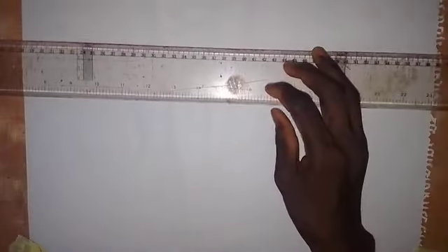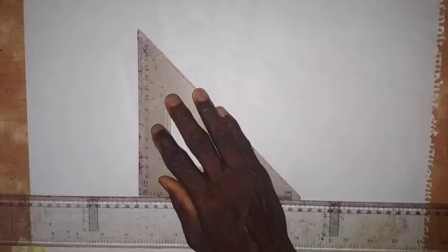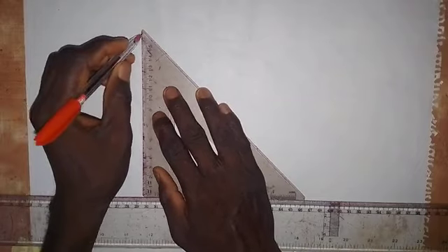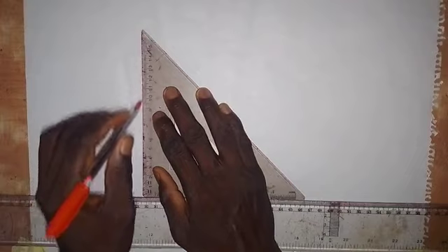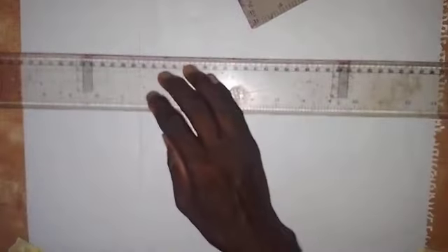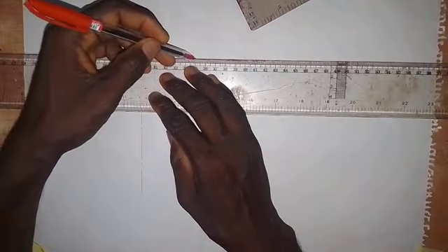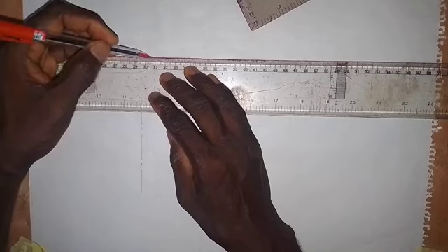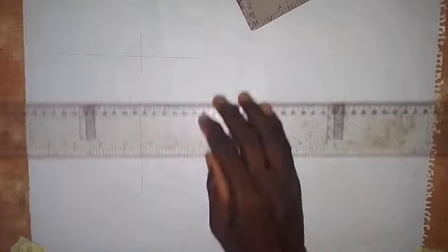The first thing that we are going to do is draw a vertical line. So let's draw a vertical center line first. I need to have a space, so around here. Here we have the vertical center line. A center line is drawn with a thin long chain line. Then I will come up here and draw a horizontal center line. So here we have the horizontal center line.